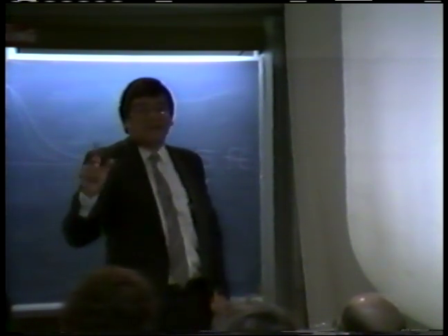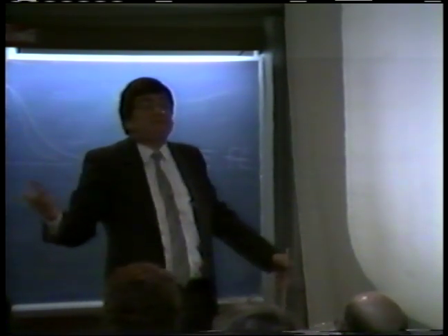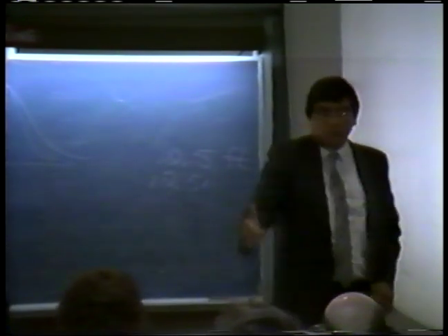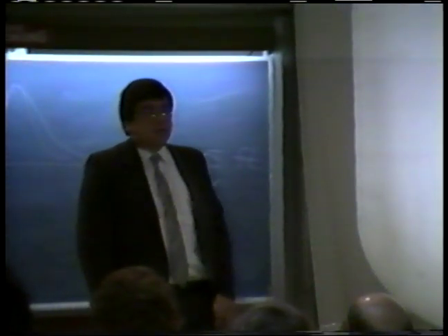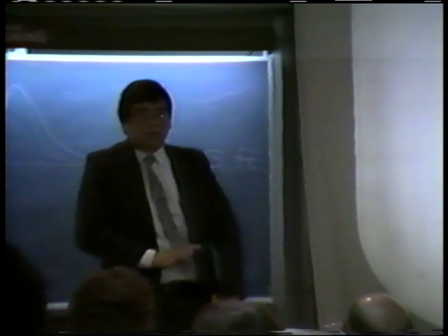Pardon me if you know, but we're civil, interested in floods, so therefore we stick with the concept of kinematic, diffusion, and dynamic wave. Out of these three, the kinematic wave is the coarsest. You cannot go coarser than the kinematic wave short of going to steady flow.